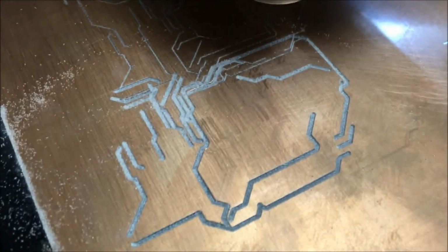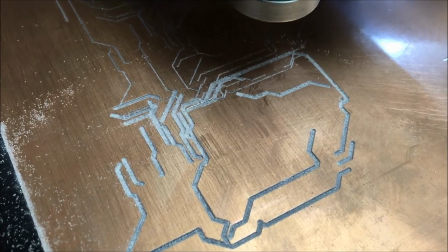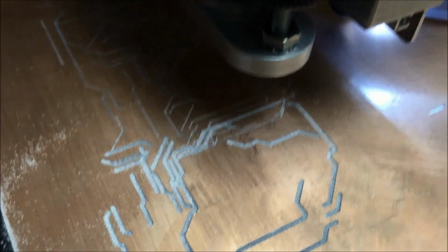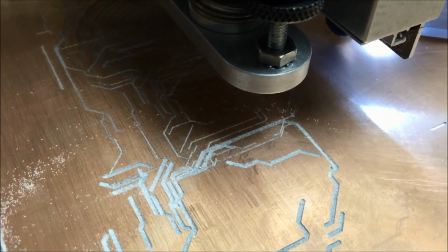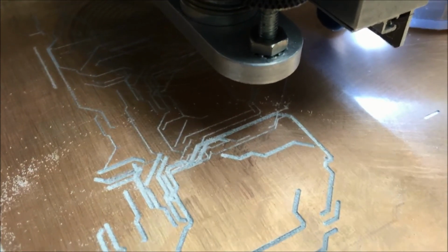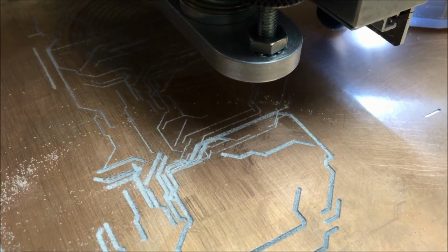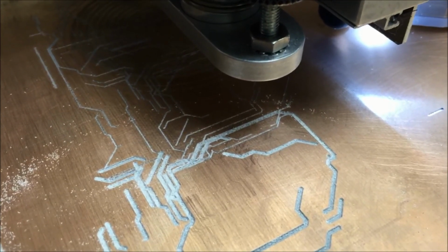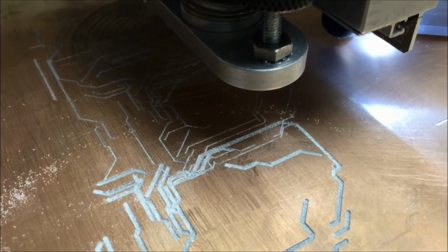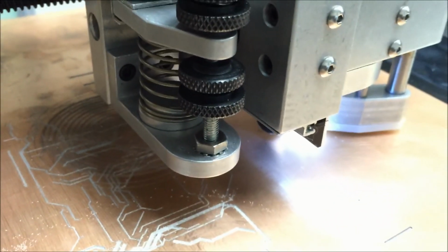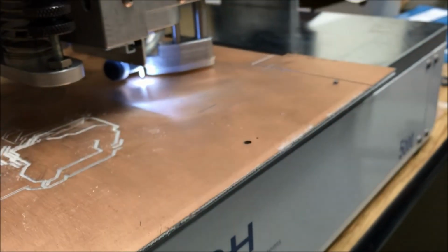To demonstrate as much as I can there. Yeah. And that's essentially as far as I've gotten. Okay. You have all of the information about tolerancing and tooling. That all comes from your Eagle design, where you would define it, and then you would make sure you run tolerance checks. Eagle has the electrical design check that would make sure nothing's too close either.